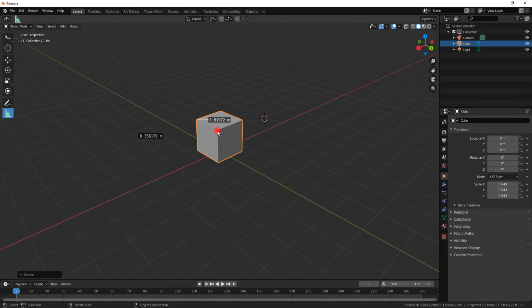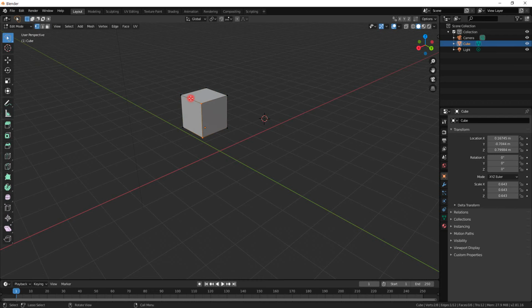Okay, so this was object mode. The modes are, by the way, up here, and you can select these modes. But you will find that you will mostly be using edit mode and object mode. Edit mode for doing vertex and edge and face level stuff. So the modes are here, and object mode is moving the entire mesh, and edit mode is for moving whatever it is that you have selected, like an edge, like so. That's the difference between the modes.